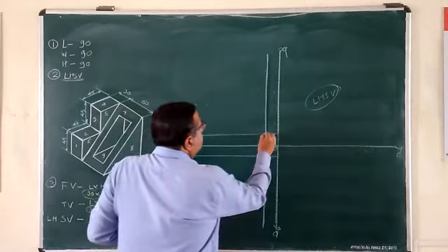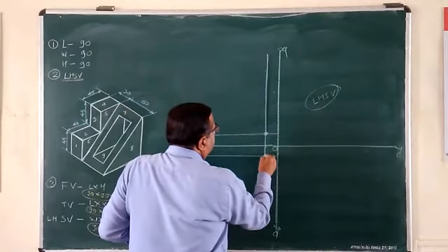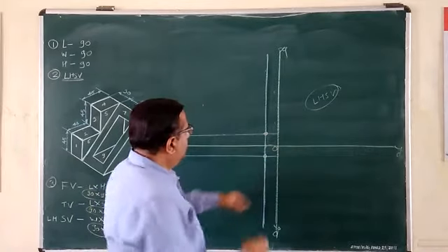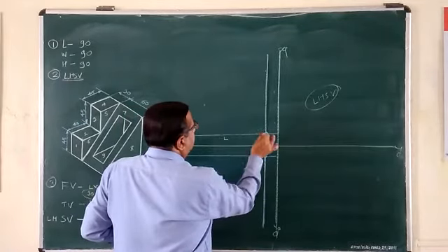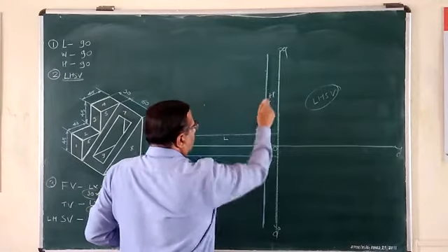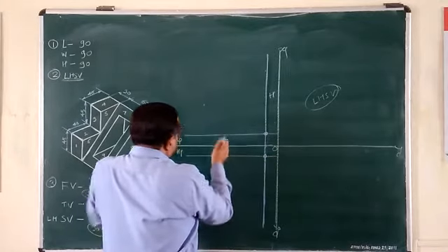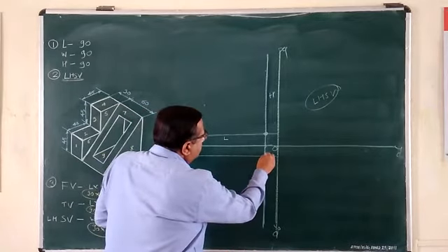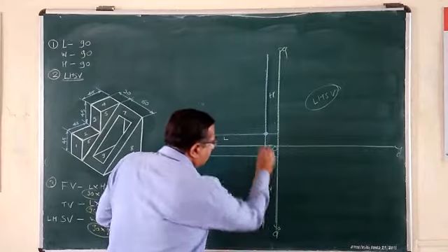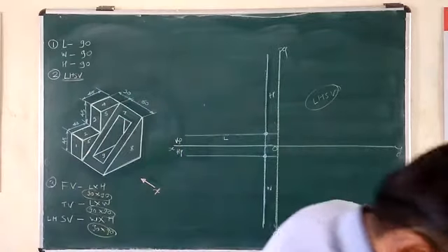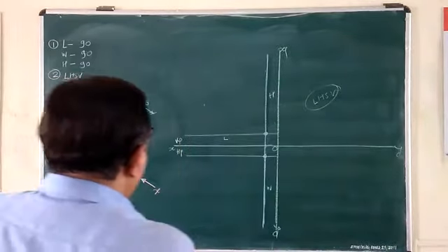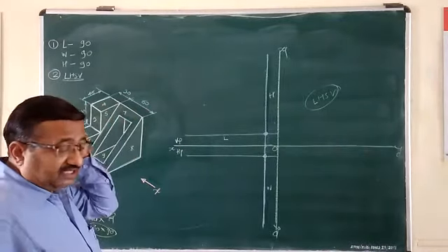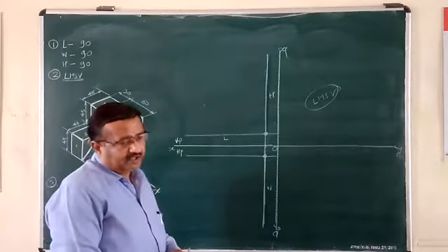Now these are the intersecting points of both construction lines. These are the starting points from where we have to mark the length on this side and the height above this dot. Similarly, from this dot, the length will be carried forward automatically with the projection lines. Separately, below this dot, you have to mark the width of the object. I will first complete the areas: the front view and top view areas, both at once.